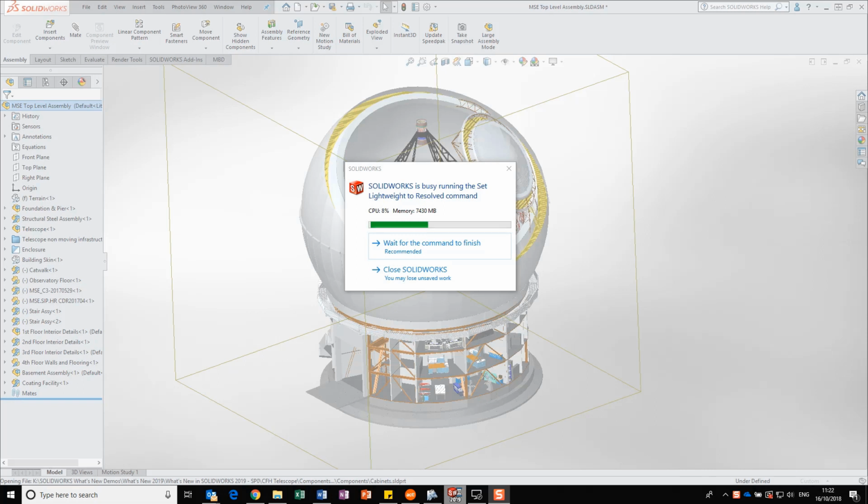In SolidWorks 2018 and previous, anyone working with large assemblies or doing complex heavy features will have probably come across the Windows "not responding" message. That is a Windows message and appeared if you clicked and the previous command had not completed. Often when confronted with this whiteout page, users assumed that the software had hung or crashed and would end the session. Quite often, if you waited, the software would actually start to respond again.